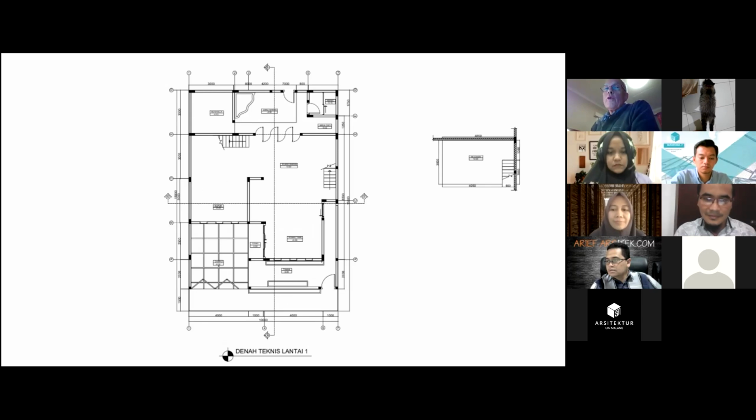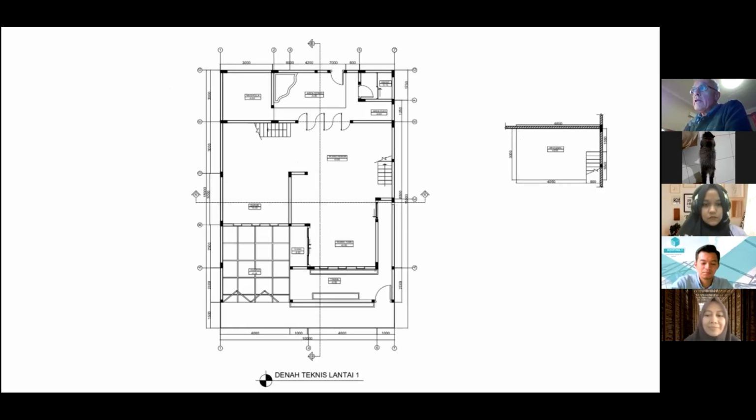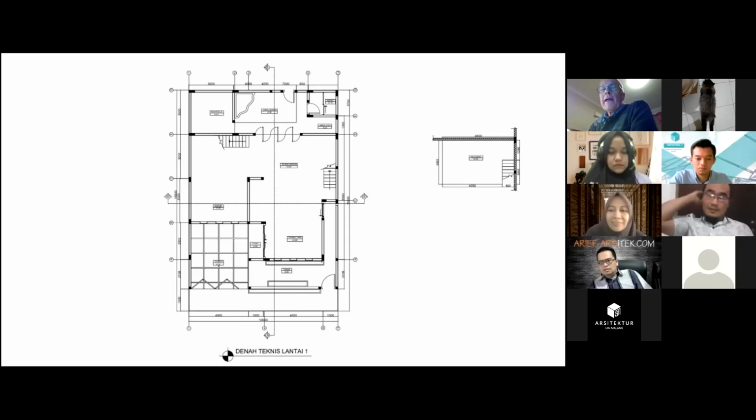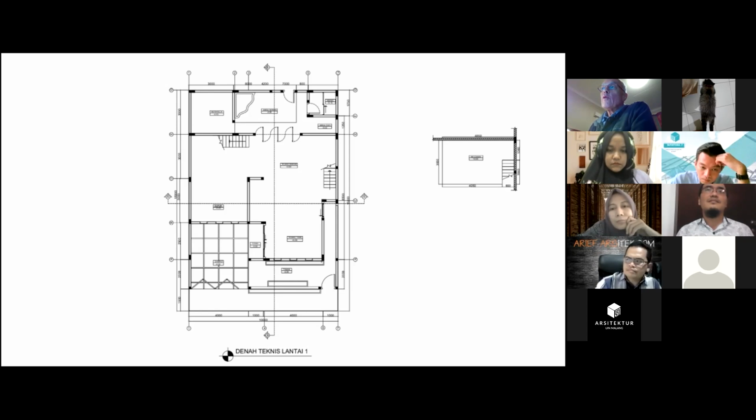However, the question really is, is the vertical structural system a post and beam system, or like a moment frame system, or are the walls load bearing? Could this be a system using confined masonry, where we are not assuming frame action, but we're assuming load-bearing walls that are confined with tie columns and tie beams? Or are we having a combination of those two systems? And that is possible.